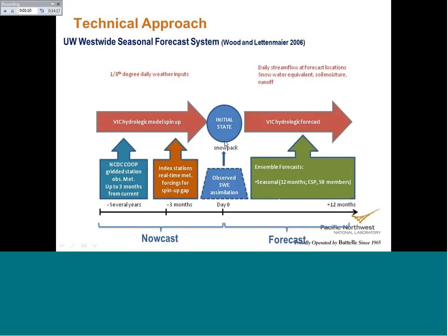as soil moisture. From this, we further force the hydrology model with ensemble seasonal forecast. There is an approach called ESP, ensemble streamflow prediction, where especially for snow-controlled basins, the different forecast traces are in fact something from the past. It means that we think there is little information in the climate, and the forecast is mostly driven by initial conditions. So this is the seasonal forecast that we are actually using in the system, and this is widely used in the Western US as well.